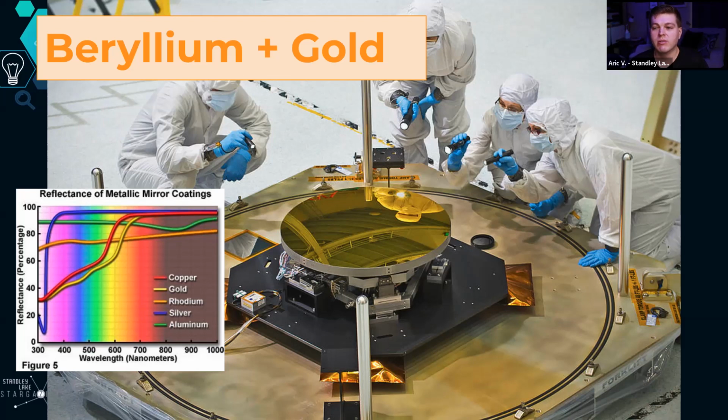So probably a little over 100 degrees in the summer, probably below freezing in the winter. In that range, it's still going to have some elasticity to it, so it'll give and take a little bit. It can bend without deforming, things like that. But if it gets really, really cold, just a few degrees above absolute zero, it's probably going to become so brittle that any load or transverse load, the shear stress on the side, will cause it to fracture, and then you can't use any of it at all. It doesn't absorb anything anymore. It resists, and then it breaks with much more stress added to it.